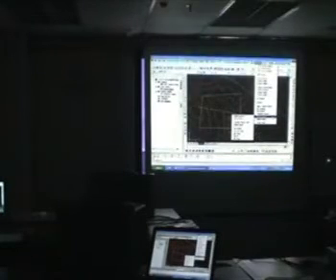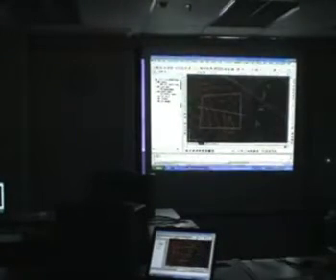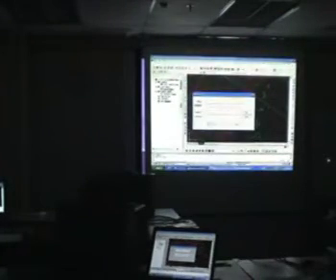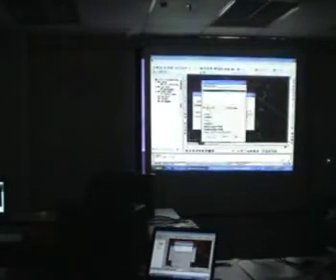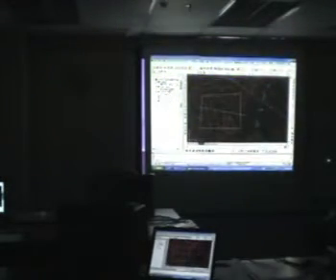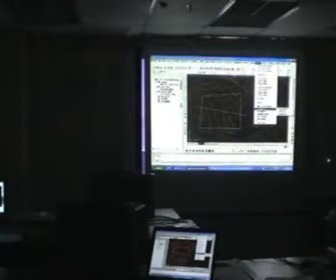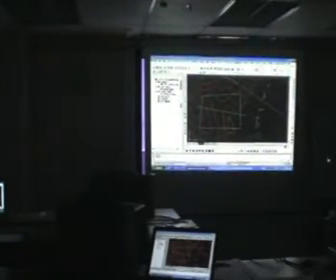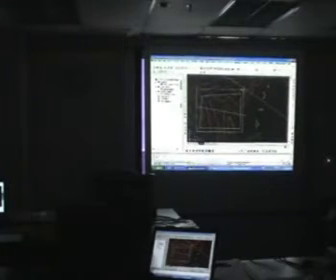So I'm going to show you all 3 methods and show you how easy it is to use. First, we need to specify our stratum. We specify which is our original level, that's surface 1, then which is our proposed level, surface 2. And then next we need to define our site, because sometimes we have such a big area that maybe we only want to do the volume calculation for one small area. So this is what the site definition is for. I'm going to specify my base point, which is the lower left corner of the area. Specify your grid size. This depends on your project, of course. Every project has a different grid size. And this is the site which you're going to use.